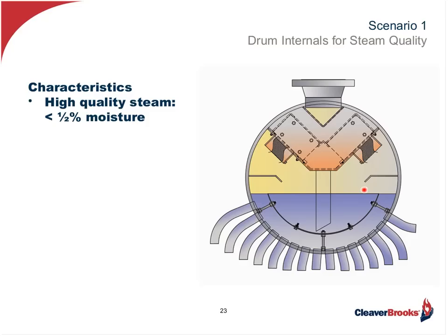That means that with a fire tube, if I were to apply one to an application that's requiring high quality steam, I would have to have an inline separator within that steam piping, within the header piping, to trap the moisture. That would be a centrifugal separator. Adds additional cost, and of course, budget is a consideration in this scenario as well.